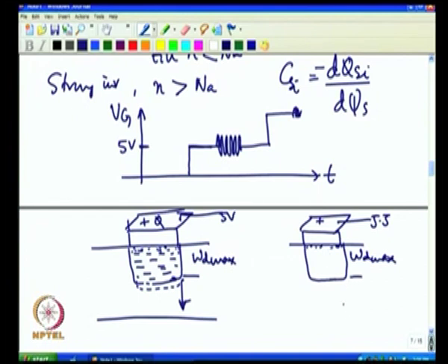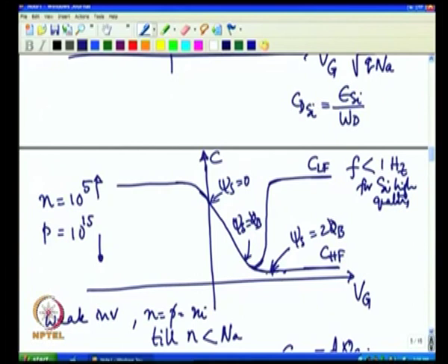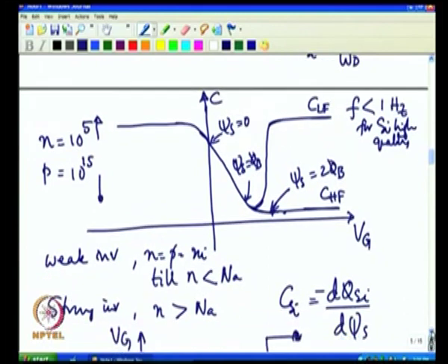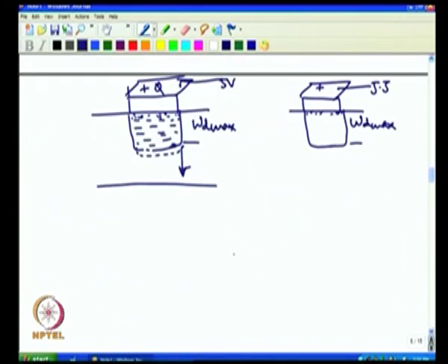It is only the edge of the depletion region, the holes are uncovering and covering the charge, and hence you get a constant capacitance, a constant value which is not the same as the oxide capacitance value, which is much lower than the oxide capacitance value. And what is this value? This value is essentially your Cox again in series with C silicon minimum.